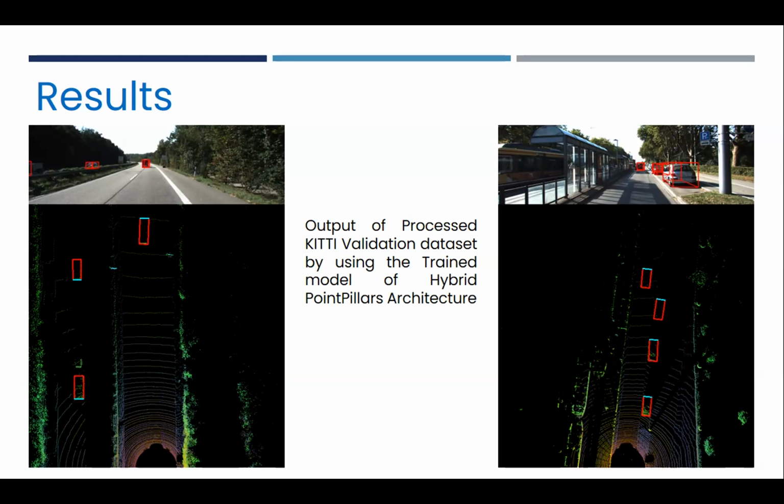While displaying, we have converted the 3D LiDAR data into a 2-dimensional format, and we have taken the top view of the front portion. Whatever area is covered in the camera data, we have taken the same area in the LiDAR data, made the top view of this, and we are detecting and marking the bounding boxes across this. So now let's talk about what exactly we have got.